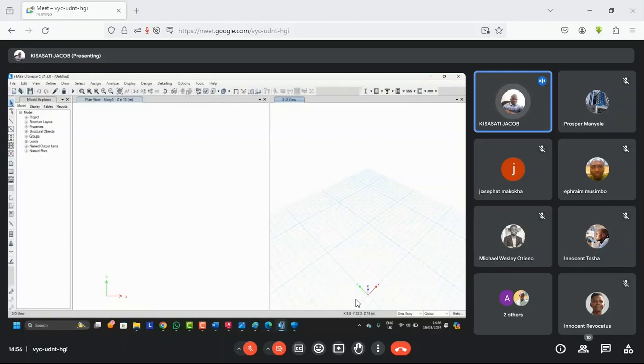How do we utilize this arrow? We just click on this window here, then they will be activated. Then you can now move to the bottom story. How do we move to that bottom story? You can just go up. Of course, from story 5, it's like a circle. It will go to the 0 story, but we don't want to bring the plan to this. We'll just bring our plan to story 1 here. So this one is okay. Then whatever we are going to create will be visible here.